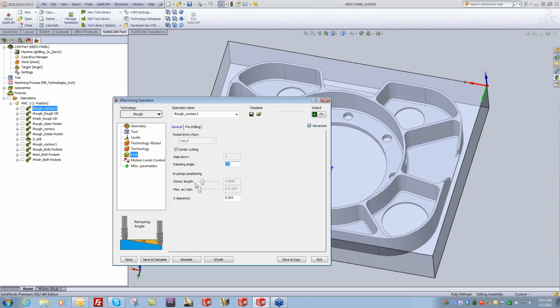The reason they do that is because the bottom of most tools are only 3 degrees. However, I can direct you to some manufacturers that create tools with a much steeper angle. It's not actually 15 degrees on the bottom of the cutter, but the way they create their geometry, you can go down 15 degrees without any problem at all. That's the tool I was using when I was testing the technology, drilling versus milling a hole, and we were able to helically interpolate a hole faster than we could drill it. That's how fast these tools work.